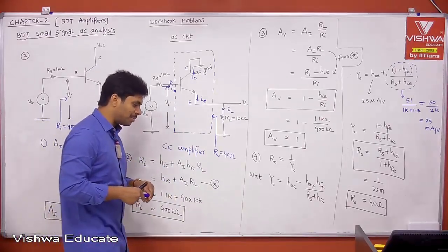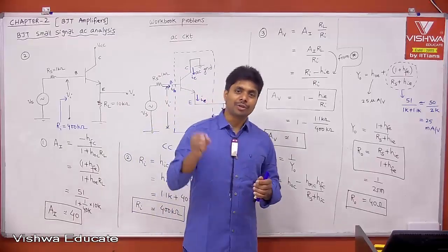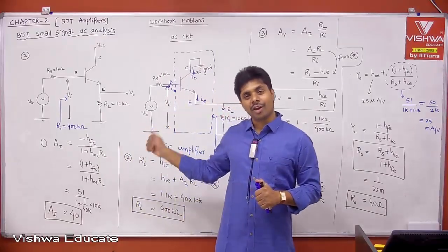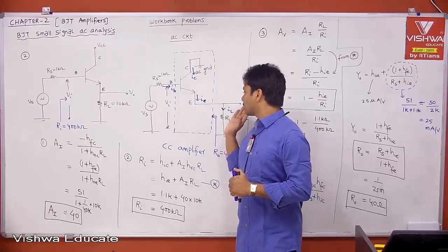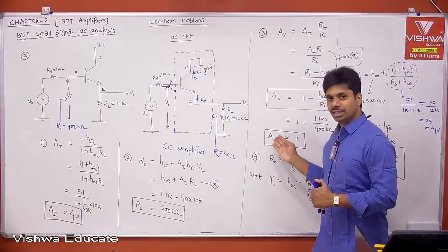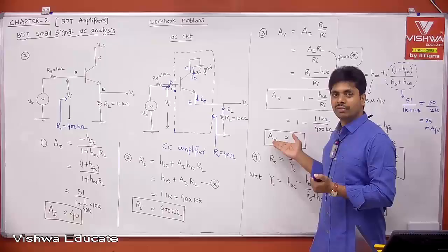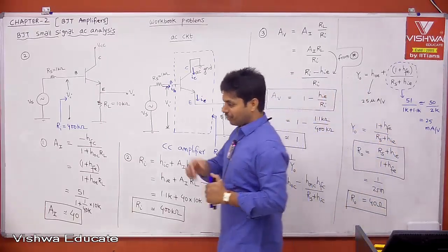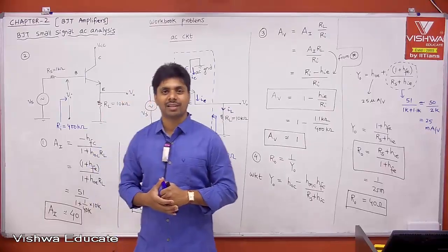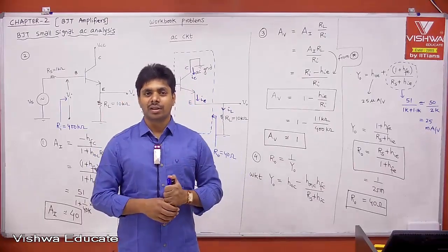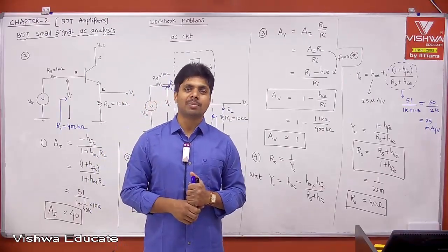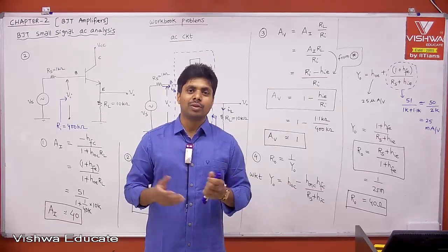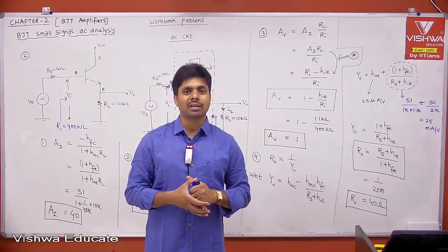See, in the case of the common emitter amplifier, we have very good voltage gain, but no impedance matching. Here, we have very good impedance matching, but there is no voltage gain to utilize. Yes, we can utilize it as it is without any loss, but the available voltage gain from this configuration is nothing but 1. Therefore, if you want something, you need to lose something. If you want voltage gain from the common emitter amplifier, at least 200, but we don't have impedance matching, that's fine.